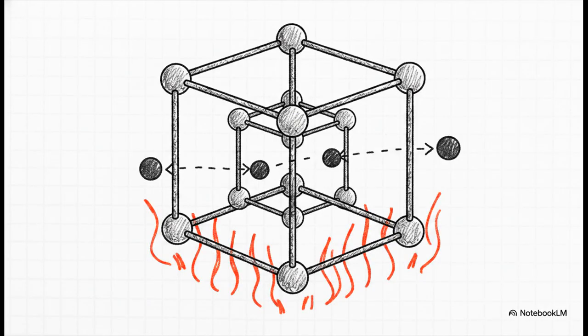That empty 41% space in the center of the austenite structure is exactly where other elements, like carbon, can hide out when steel is heated up. When the metal shifts into this FCC structure, that giant microscopic void opens up, acting almost like a sponge. This empty space is precisely what allows us to manipulate steel, give it different heat treatments, and harden the metal to build the super strong structures we rely on every single day.